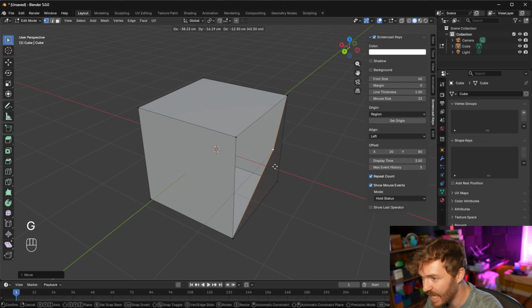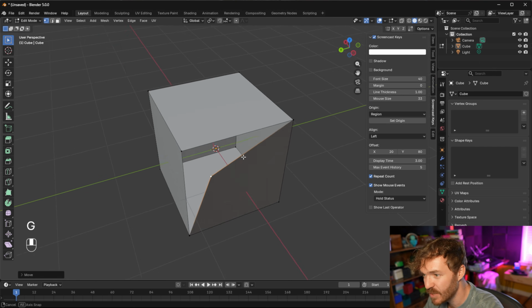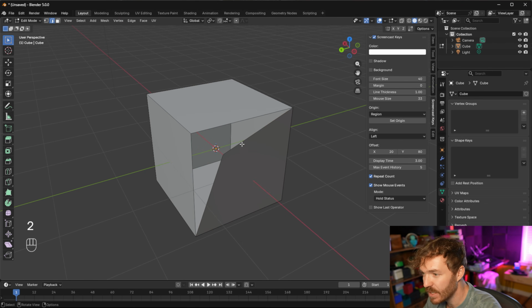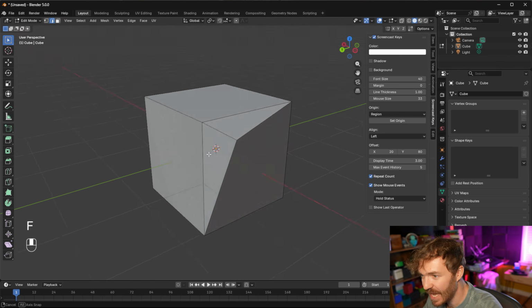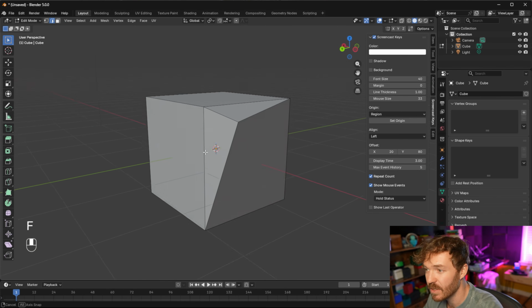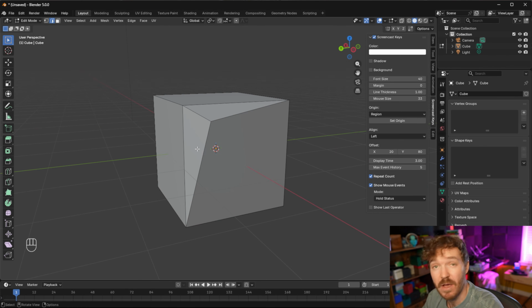Let's say we have this out here and we actually like the shape of this, but we want to fill this gap. Well, we can go into Edge Select and we can hit this edge and hit F to create a face. And then we can hit that edge to hit F again to continue the faces and block that along. That's one way of filling that hole.